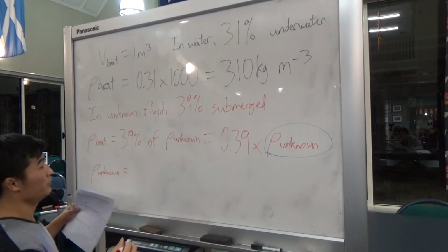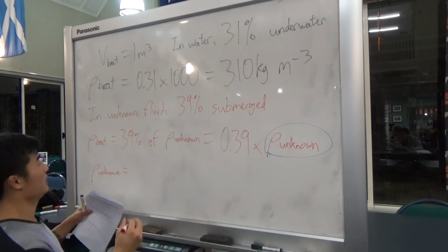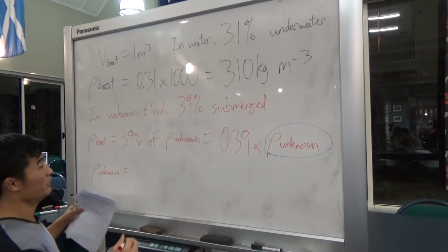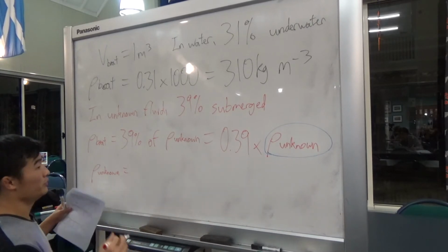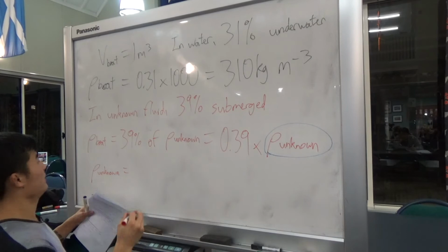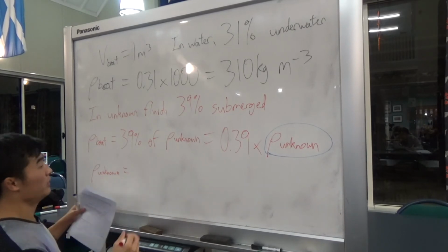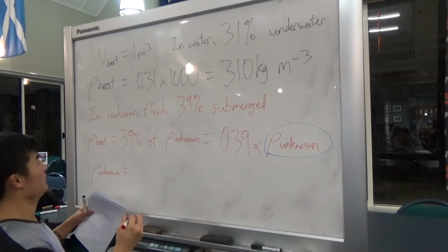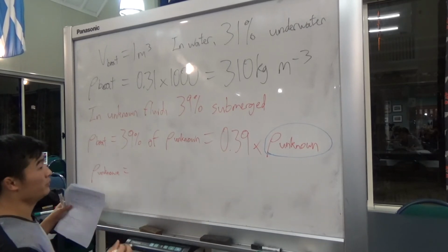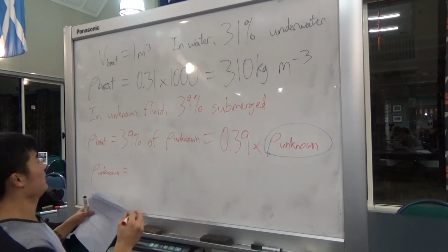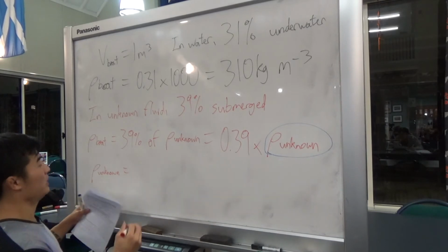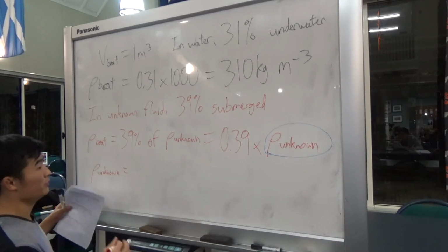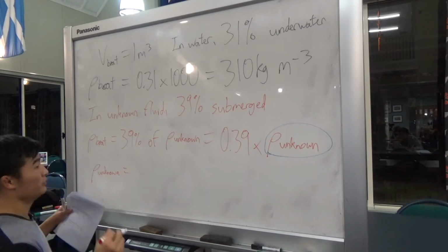Okay, and because the height's the same, we can get rid of the rho GH1 and rho GH2, because it's a horizontal pipe, which means the height doesn't change. So what we want is P2 minus P1. So P2 minus P1 is going to be equal to half rho V1 squared minus half rho V2 squared.